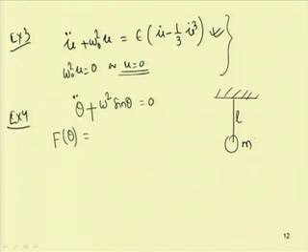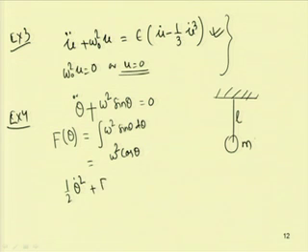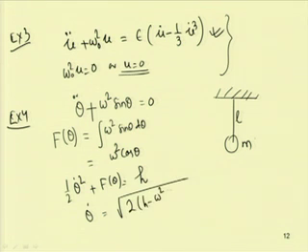that is the potential function, equal to the integration of f u du. That means the integration of omega square sin theta d theta, which can be written in this form: omega square cos theta. By integrating the equation, as we already know, it can be written as half theta dot square plus f theta equal to h, or one can write theta dot equal to root over 2 into h minus omega square cos theta.